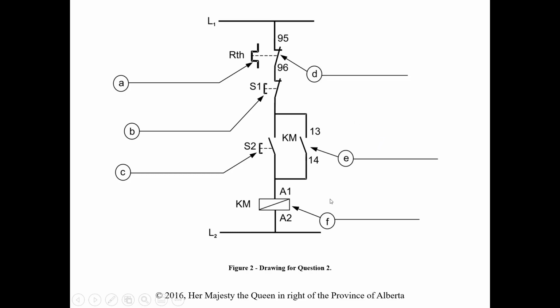Here's, again, this is for another question in your module, but this is an IEC. Again, IEC, we are labeling our coil A1, A2, different look of the coil as well. It looks kind of like a sideways version of what we would be used to seeing of our normal schematic, normal being just the most common. For a NEMA, it looks like it's been twisted 90 degrees. So here's the rung here, and here's a rung here. And then the side of the ladder, I guess, and here would be the rung here.